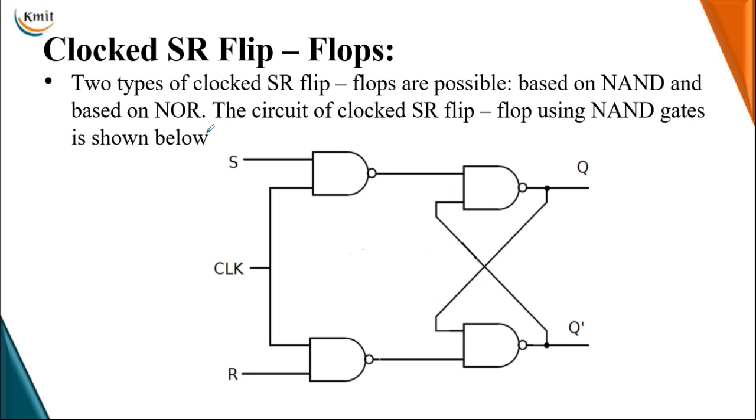Here I will mention the number of NAND gates used to construct the SR flip-flop, which is four. Gates 1 and 2 are used to obtain synchronization with the clock signal. Gates 3 and 4 are NAND gates acting like an active low input latch, a NAND latch. Until the clock is 1, no input will change the output of the SR flip-flop.